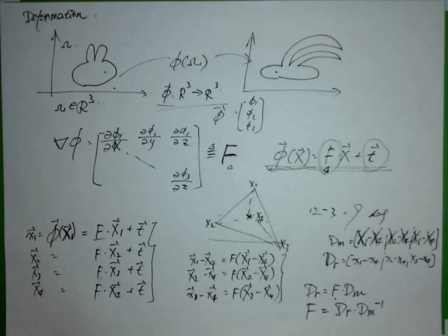All right. So one thing is that if the rest pose of the material doesn't change, if we are simulating hyperelastic materials, it always will go back to the rest pose. There's no plasticity of the material. The Dm will not be changed. So we only need to calculate it once for all the elements because the rest pose is there. We are not changing it. Calculate it once, and then we can use it forever.